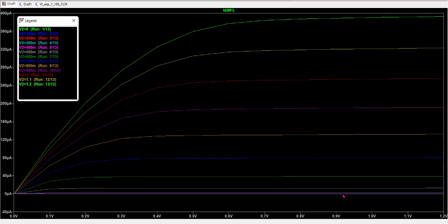Because of the built-in electric field, the charges with a constant velocity will just surpass the pinched off region and reach the drain. So from source to drain there is a flow of charges, and that leads to the current. And here you can see that the gate to source voltage is also controlling that. So this is what is a transistor action, right? We are controlling VGS, and according to that we are getting ID. So is this clear?